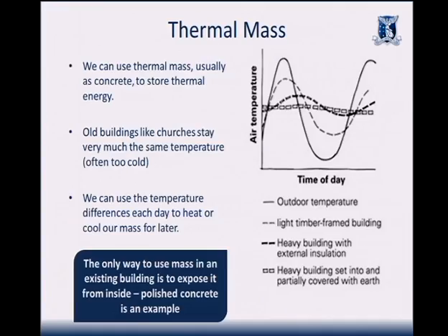You've no doubt seen that type of graph, so I won't go over that again, except to say the outside temperature fluctuates. The more thermal mass you have, the more stable the temperature is going to be. If I put, say, a brick, something heavier, a cubic metre of concrete, so a pad footing, I'm sure we talked about pad footings, cubic metre of concrete, sit it outside, say on the concrete lawn at Albanyini, what temperature is it going to be? Sorry. What temperature is that concrete going to sit at? Could we predict it?